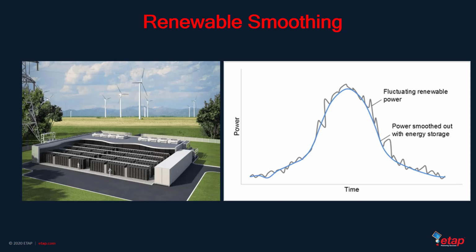So it becomes difficult to calculate exactly what output of each generator should be in order to accomplish the load following phase. Fast fluctuations in output from wind or solar not only disrupt the hourly load following phase of grid planning, but also the second-to-second balance between electricity supply and demand.